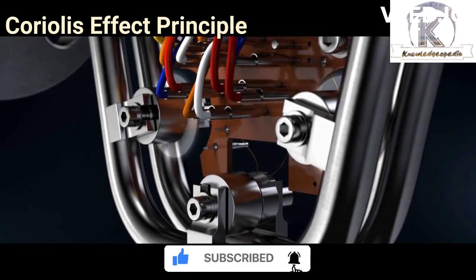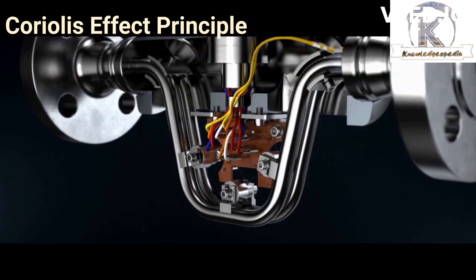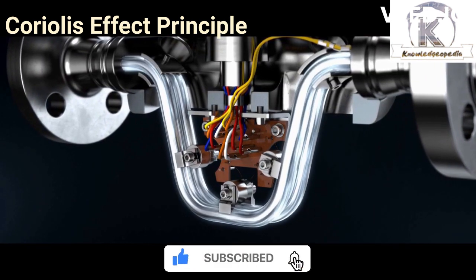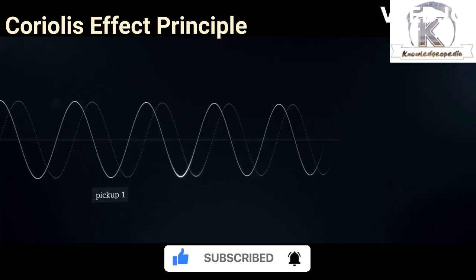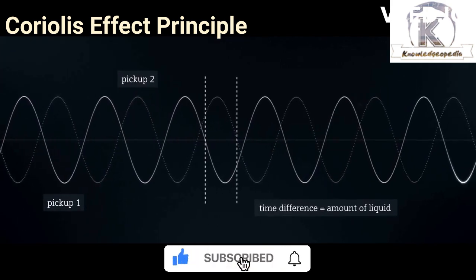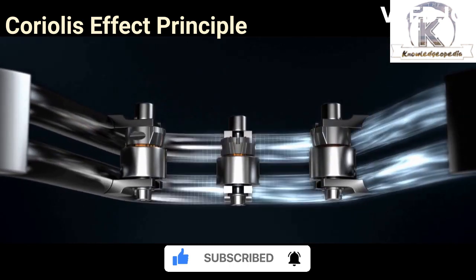Differing from the single tube design, the pickup sensors for inlet and outlet here are placed at a perfectly fixed torsion plate chamber, exactly at the metal in between the two parallel tubes. These sensors detect phase differences between the two tubes and evaluate oscillation. Based on the range of detected oscillation frequency, and with the help of some settings, medium type and status like empty, filled, or partial condition can easily be identified.